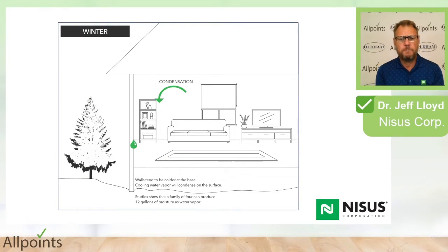And here we can see the opposite kind of problem to condensation. Here we can see in the winter months, now we've got a reversed situation. It's very cold outside, but it's wet and warm inside. And how wet inside will depend on whether people are hanging washing clothes to be dried, people taking showers and not having good ventilation or air extraction, cooking, generating moisture, etc.